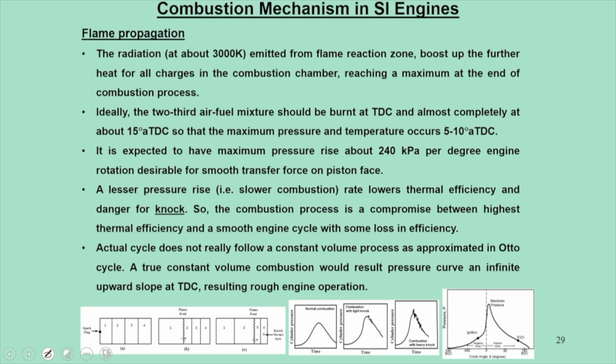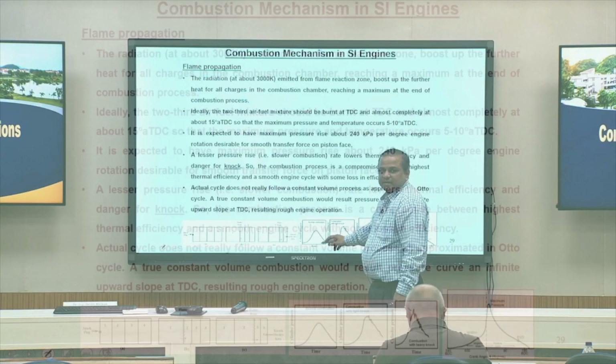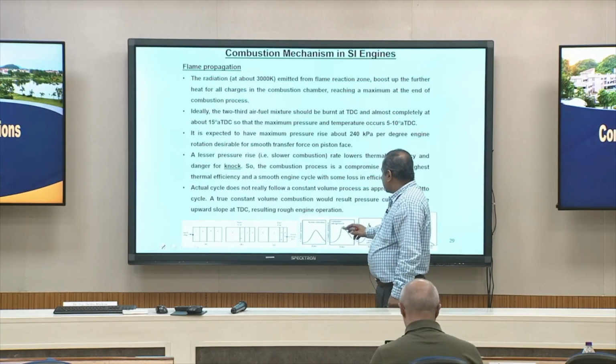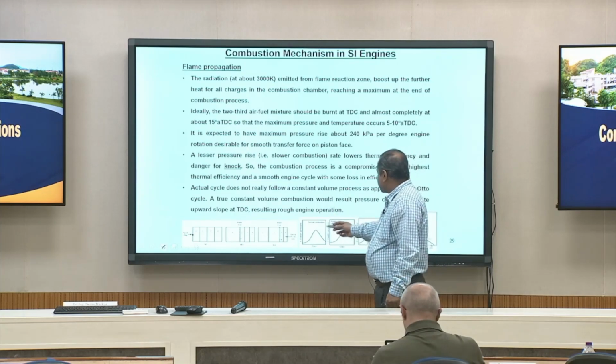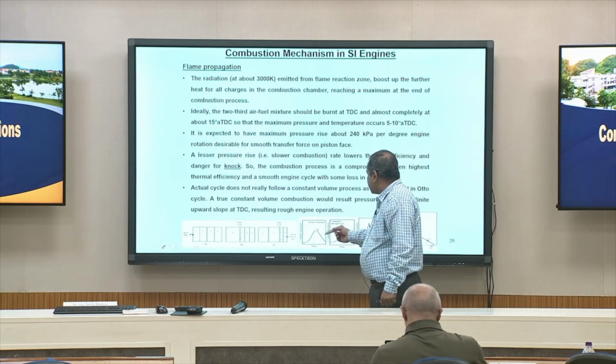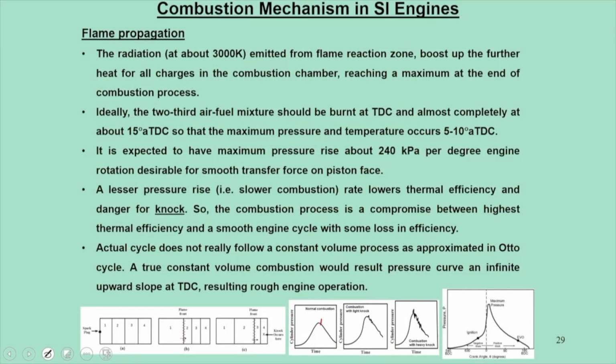For normal combustion the pressure-time trend is smooth. Now when there is a slight knock, because the highest pressure is felt at this location where the equivalence ratio is close to 1, at that point of time we see pressure pulses in an erratic manner. That is a tendency of knock or higher pressure pulses, and with heavy knock these oscillations become more significant.